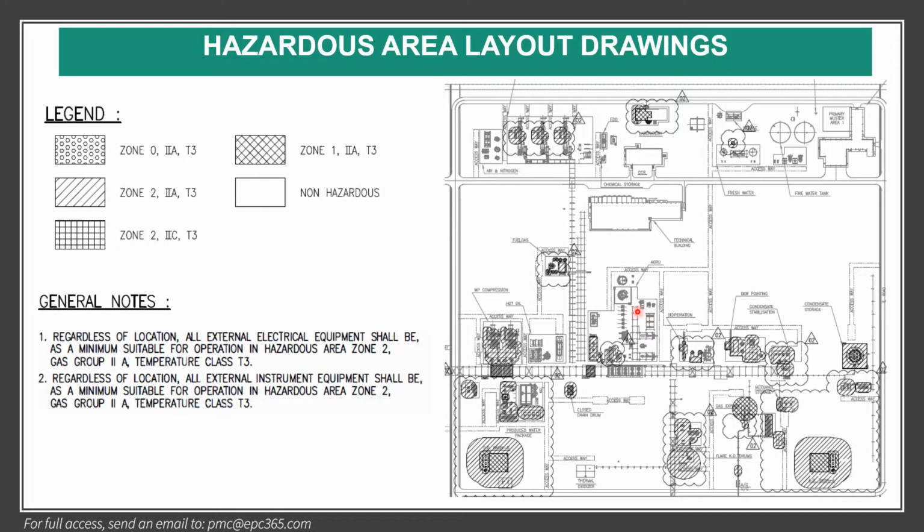Also, the objective of the hazardous area classification is to put an airlock if we have a door in the restricted area, and also to put a gas detector in an intake to stop the dampers or stop HVAC in case of gas ingress in this area.